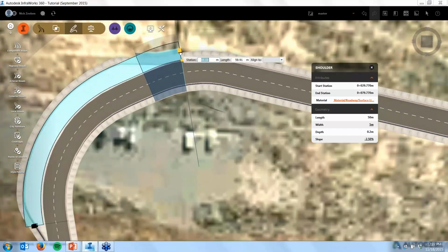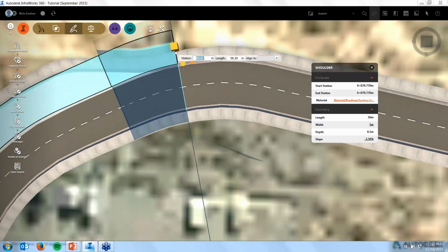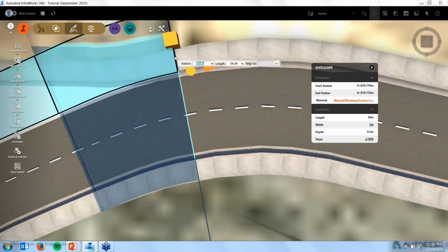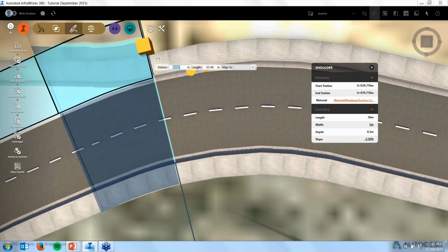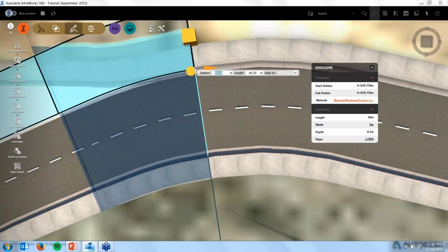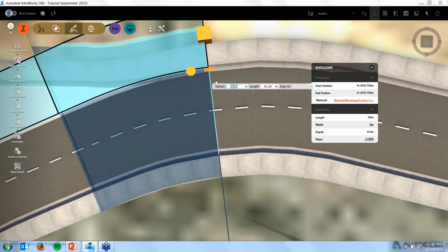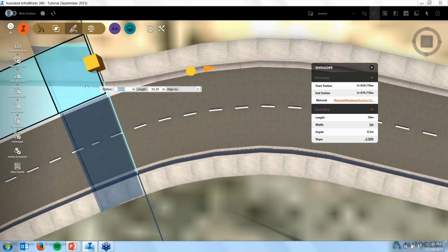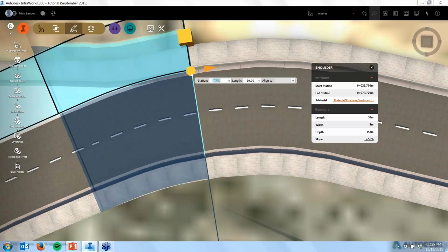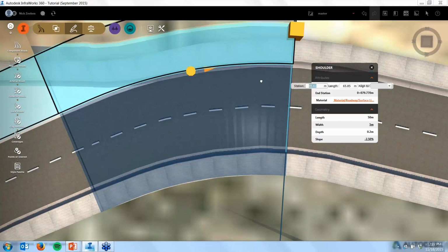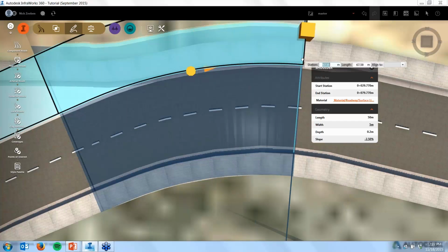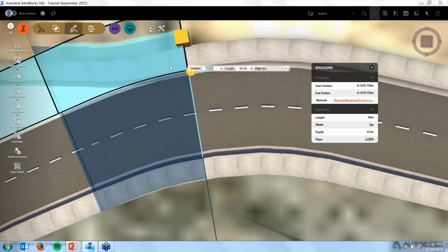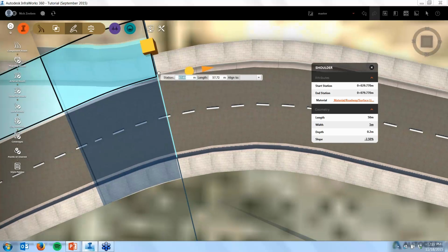So I'll zoom way in so we can see them. Here you can see when I'm dragging the shoulder, there's this dot and an arrow. What those indicate is places that I could drag this element. So in this case, at this particular location, I can continue along this seam or joint between the curb and the sidewalk in order to stretch this element out.